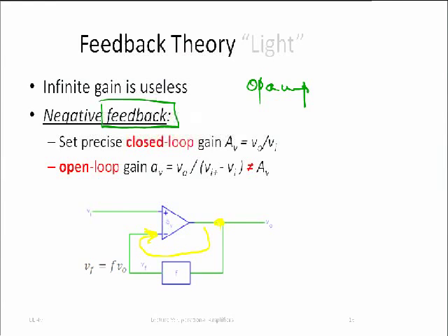Whenever you see one of these triangles in a circuit diagram, that's an op-amp, so look for the feedback loop. The second thing to look for is that the feedback can go to either this terminal or this terminal. It can go to the plus terminal, or it can go to the minus terminal. Conveniently, this is called negative feedback, and this is called positive feedback.